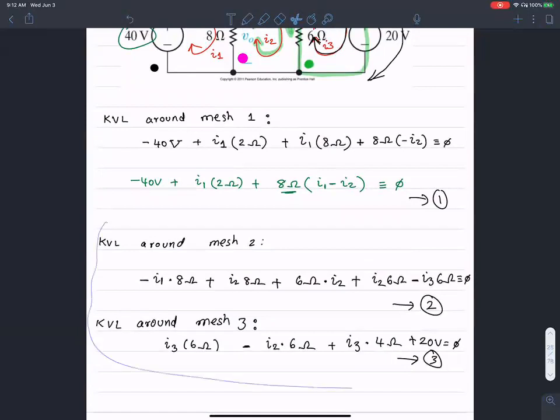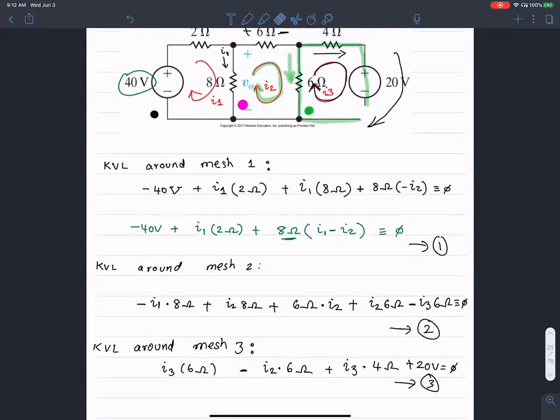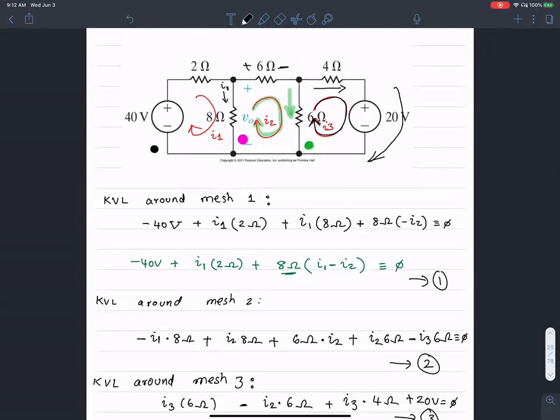So basically, for independent sources, when the source is leaving as a negative, it becomes a positive, and when it's leaving as a positive, it becomes a negative, right? Yes. And when you compare these two things I have written, the idea is the path that I follow. You see what I mean? You have to follow the direction of the current. When you're going from top to bottom, the current is going that way, and you encounter a plus followed by a negative, then you deem it to be plus, passive sign convention. In the other example, when you're going from negative to positive, as in here, then you account for the negative sign over there. That's the negative 40 volts. Does that make sense? Yes.